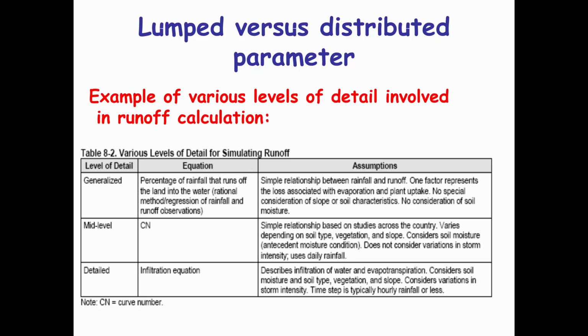The soil properties in that grid cell are well defined, and the infiltration process would be simulated with an infiltration equation that would determine the rate of runoff being generated during the rainstorm event, not just how much occurs for the entire rainstorm event.